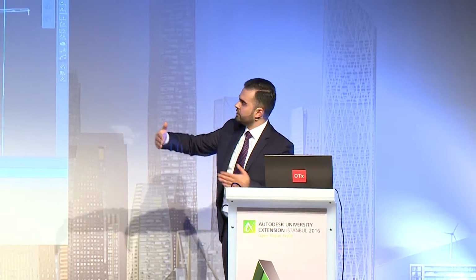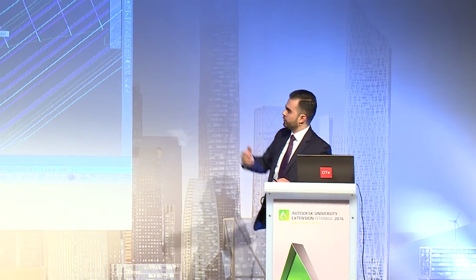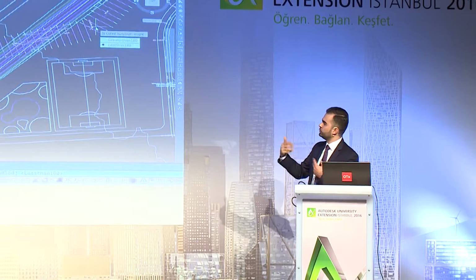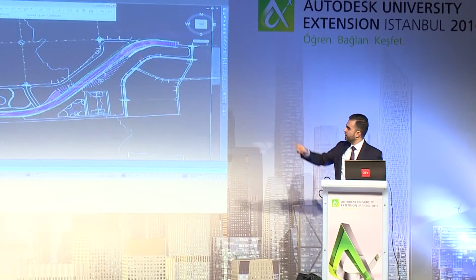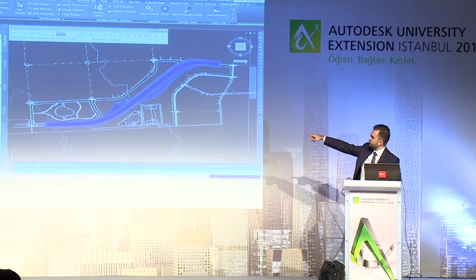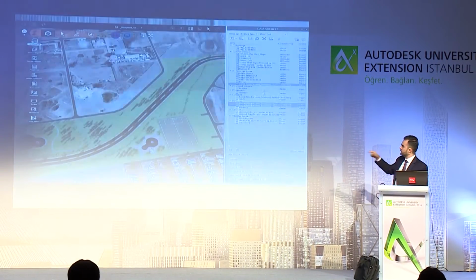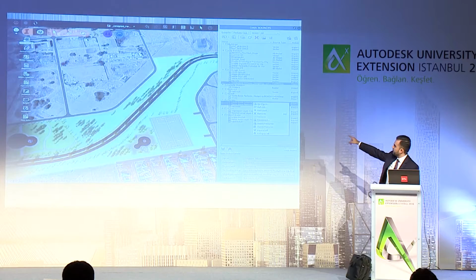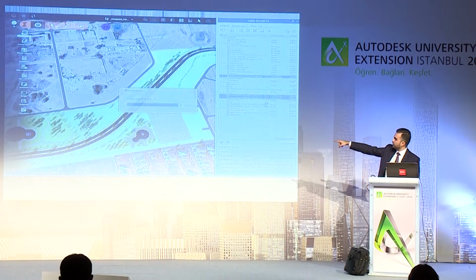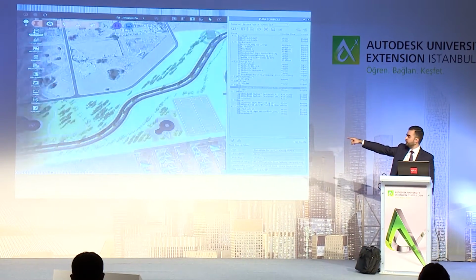And let's suppose that the civil engineer wants to update or change the corridor of the road there, right? We're changing the alignment, we're regenerating the corridor. See what happens in Civil 3D. And with a single click inside of InfraWorks, I'm going to the data source, right-click, refresh, and how that directly updates in 3D life.